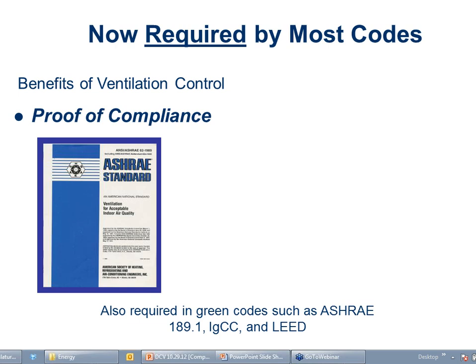So say you got 500 CFM per person in there, and you guys that have come to my classroom training have seen this because I put the sensors on the table. If I'm going to have a 50-person class, as people start walking in there, by the time I get to 20, 25 people, I've already seen the CO2 spike up to 700, 800, and then the outside air damper, if I have a CO2 system, would start reacting to that. If I don't have that system, obviously it's not going to react to it, and I'll just get a higher level. So it takes 30 minutes to equalize, not 30 minutes for it to start reacting.